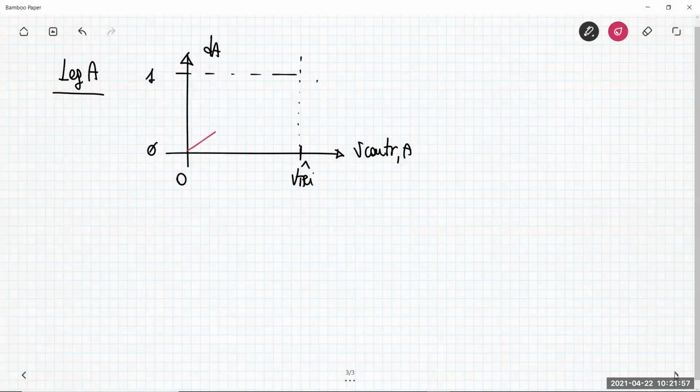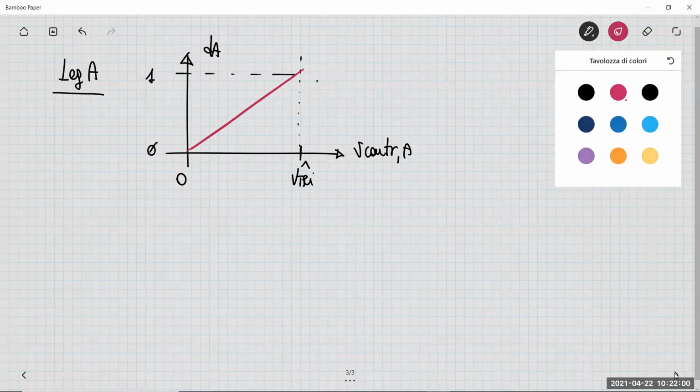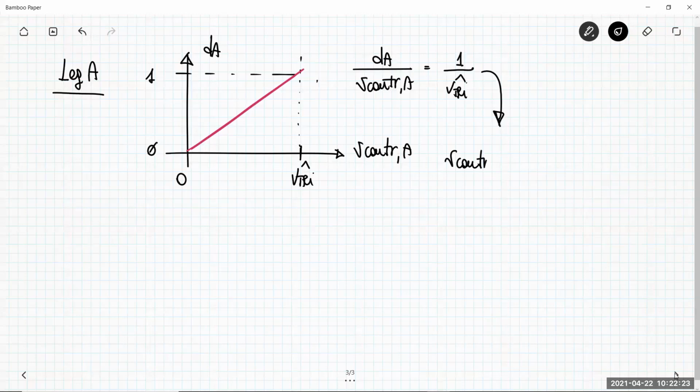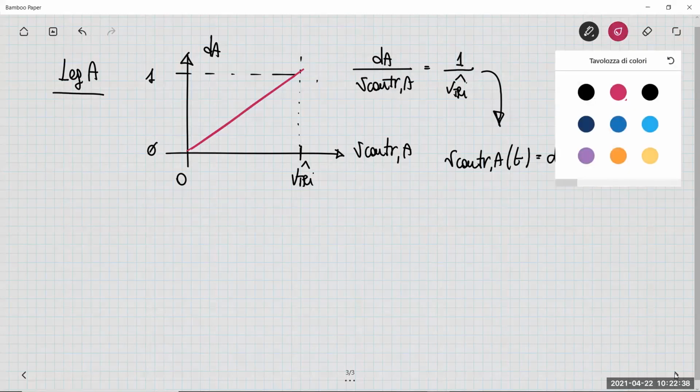So here you have something with a transfer function that is easy to derive. The duty cycle dA is the control voltage A over the peak value of the triangular voltage. Let me put this expression in this form. The control A is dA multiplied by V triangular waveform.